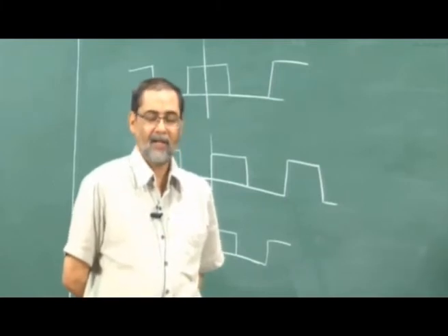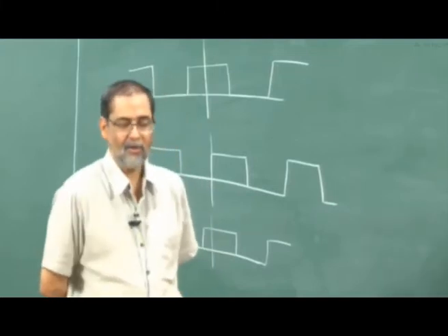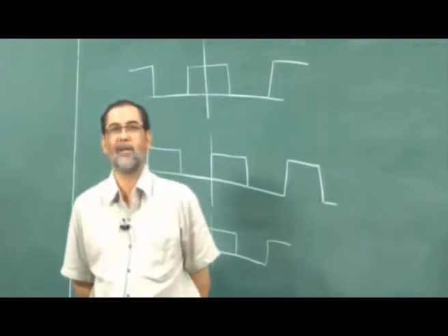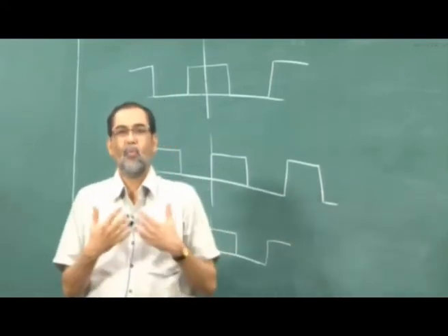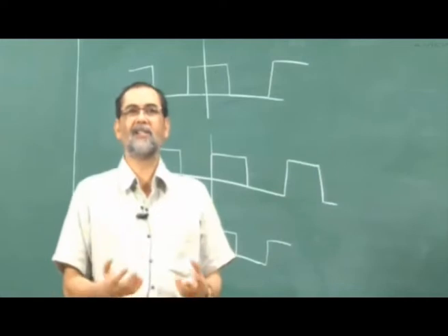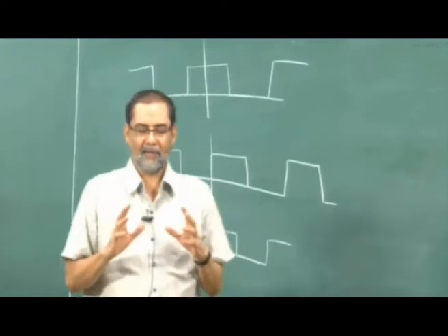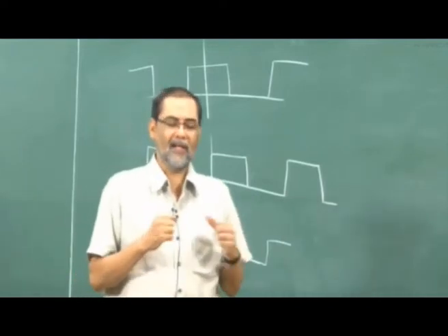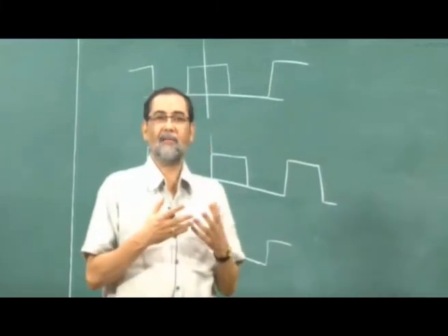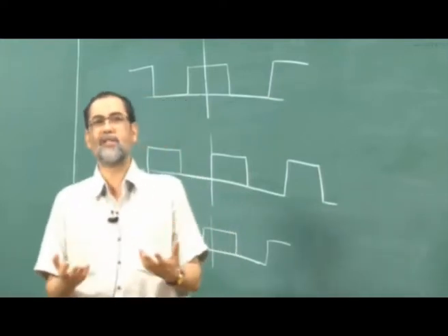But please understand that impulse is not your regular function or a regular signal. Unit step is not a regular function, and similarly signum also is not a regular function, right? We deal with regular functions, and whatever analysis we have for regular signals, we have extended that to include all these things. If you strictly go by the ideas of existence, which I'm going to talk about soon, an impulse function is not a regular function, and it does not have Fourier series or Fourier transform.